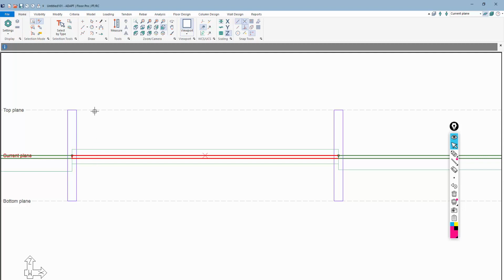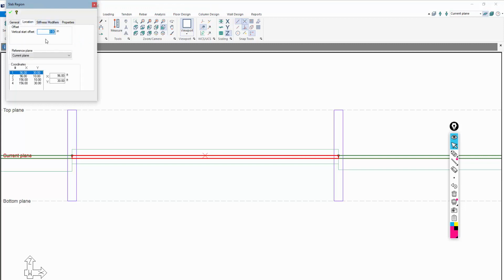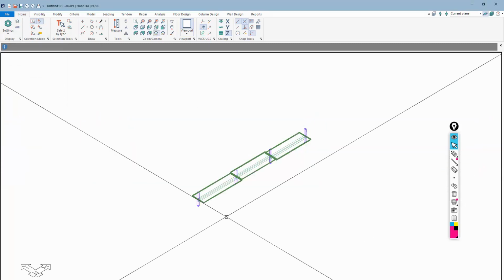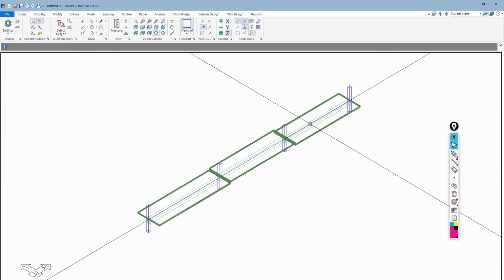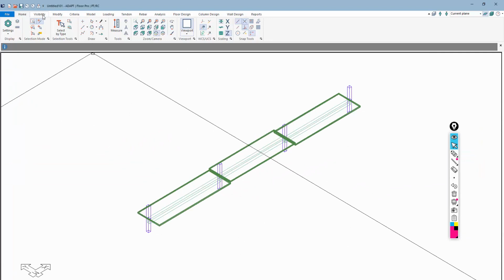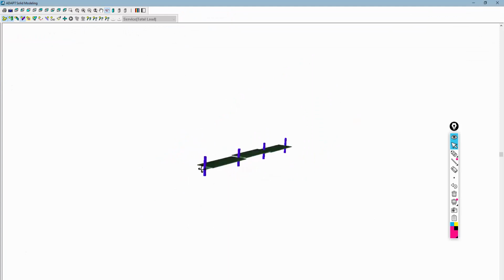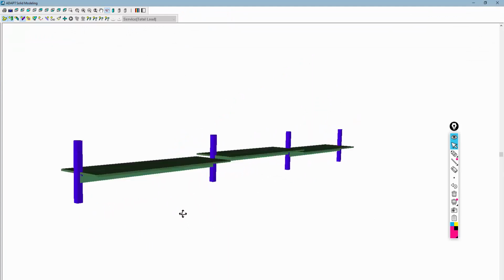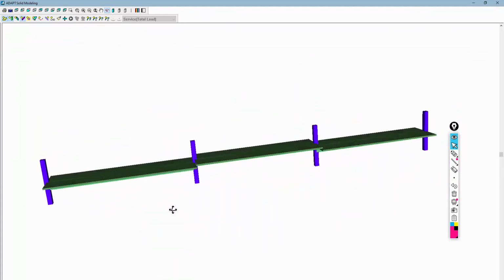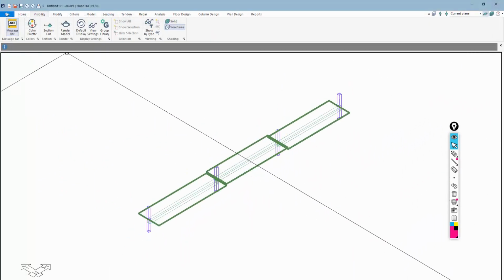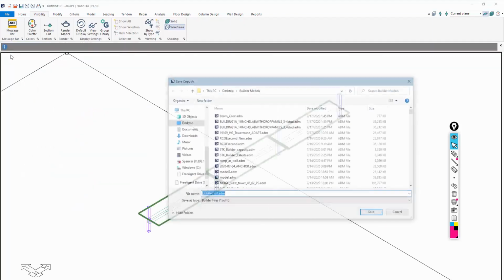push that slab upward, and I'll go ahead and just offset the slab also. So we'll take that slab location wise and we'll raise that up to 16 inches also. And now what we have is this model. So we have a stepped beam in the middle. Visibility wise, if I go to visibility rendering, you can see there's the model right there. Okay, so you can confirm it here. And let me just go ahead and save this model.